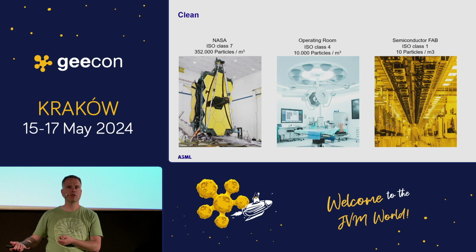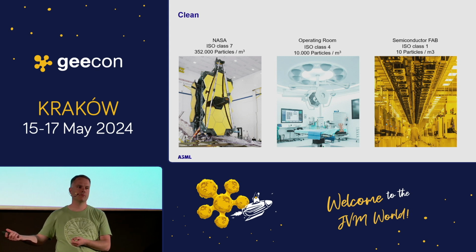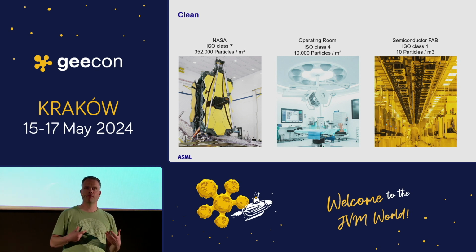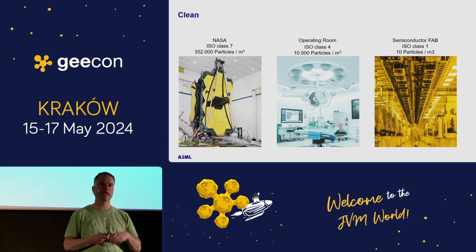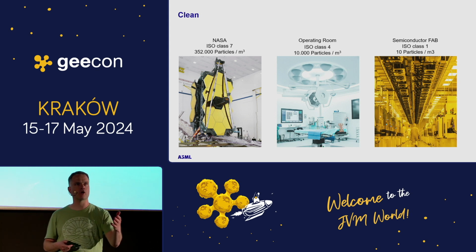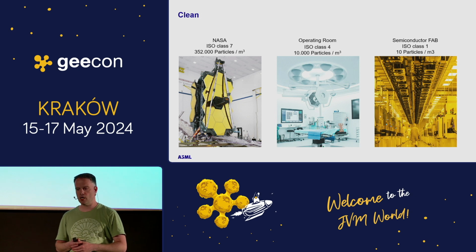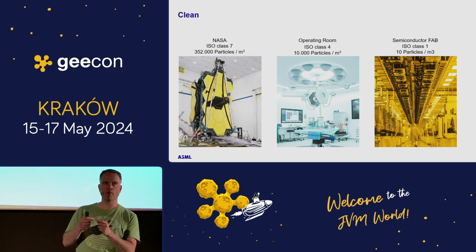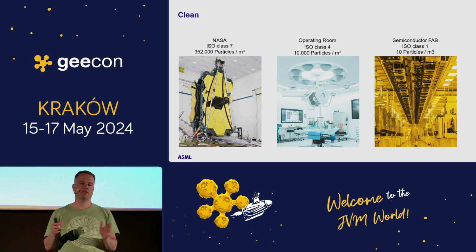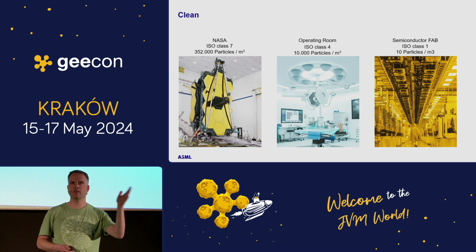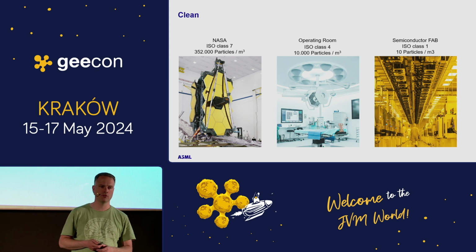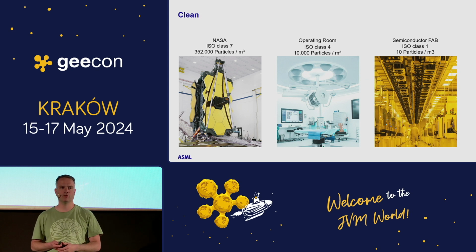People working in our clean rooms and in our customers' clean rooms cannot wear perfume. The perfume particles already interfere in this process. They can already contaminate our wafers, our machines, etc. So it's really these small particles, you cannot even see them, that influence. So they have special airflows in it, to make sure that everything is as clean as possible so we don't have issues with our chips.